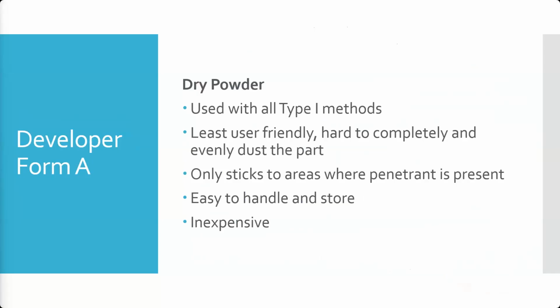It's easy to handle and store because it's a dry powder. You don't have to really worry about it leaking. They do put expiration dates on it, but it's pretty stable chemically. And so it's easy to store. Just know that you've got to be careful, if you pull the lid off the container too fast, that it doesn't get airborne and go flying everywhere. And it's fairly inexpensive. And so, that's an advantage, particularly if you have like a high volume thing, or if you're working in like a general aviation shop. But that inexpensive part, a lot of other stuff has come down, so it's not as big of an advantage as it used to be.